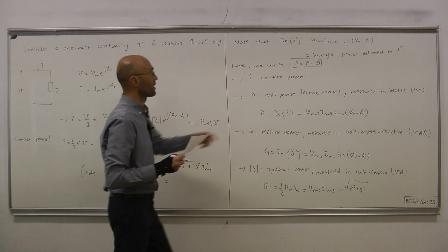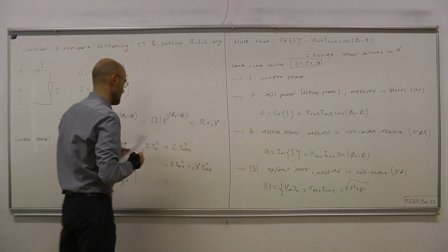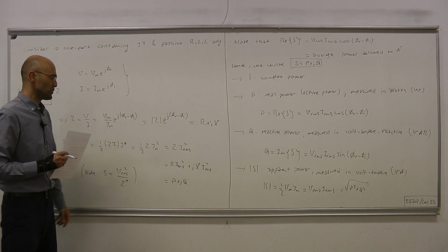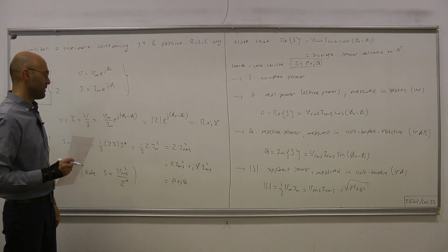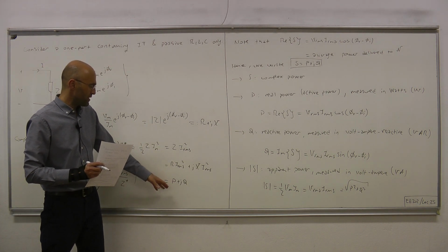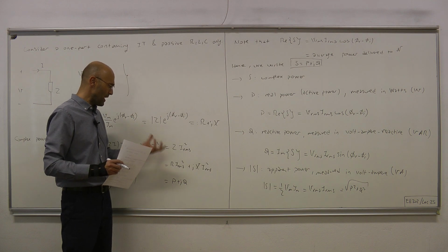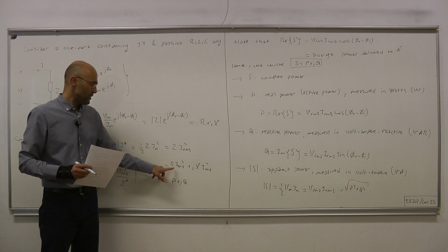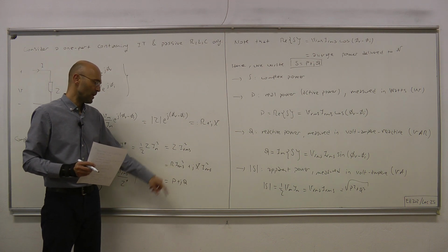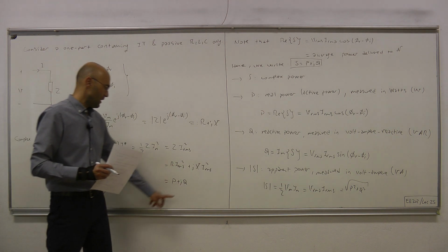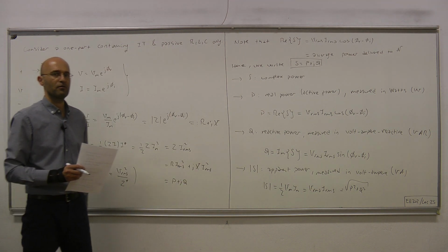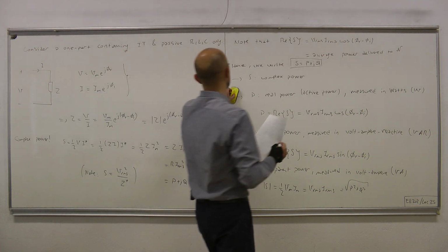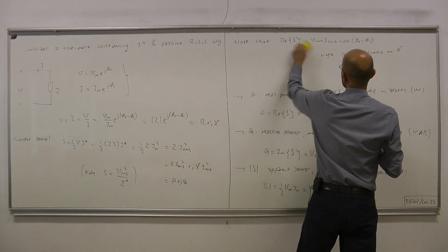We also know that S equals P plus jQ, and that puts everything in a clear way, namely the relation between S, P and Q and Z, R and X are now clear. So P, the real power, is the real part of the impedance multiplied by the square of the effective value of the current, and Q is the reactance times the square of the I RMS. Okay, so let's therefore put those relations clearly down.